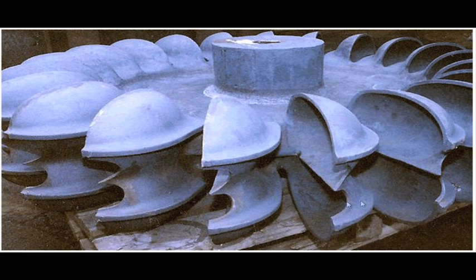This direction is the tangential, the rotation is in this direction. So, this direction and the coming out direction is almost tangential, that is tangential flow, and inlet and outlet are at the same radial location. Inlet varies with the radial locations depending upon the width of this bucket. Similarly, the outlet at different points varies, but for any section of this bucket, inlet and outlet are at a given radius.